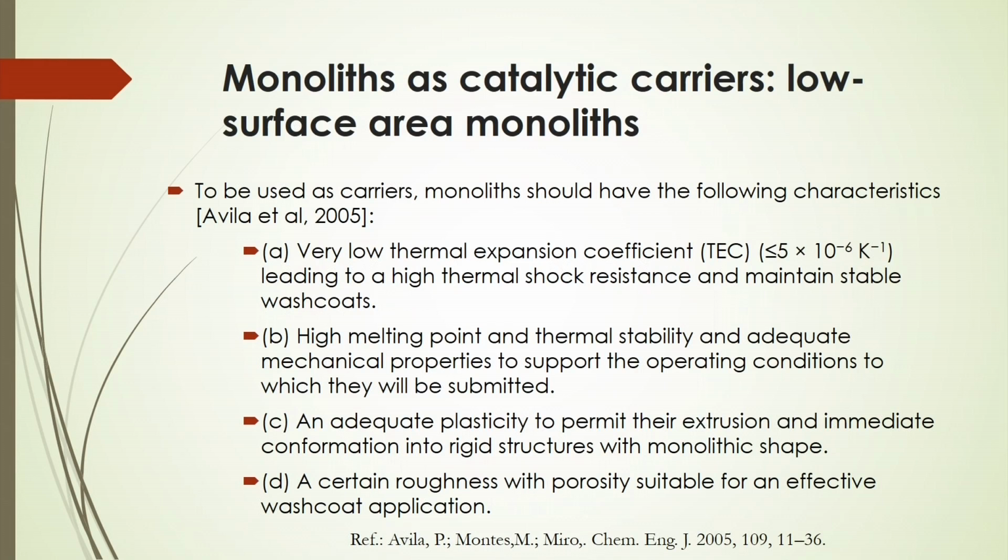High melting point and thermal stability, and adequate mechanical properties to support the operating conditions to which they will be submitted, and also adequate plasticity to permit their extrusion and immediate conformation into a rigid structure with monolithic shape. A certain roughness of the porosity should also be suitable for effective wash coat application. So, these are the different characteristics of monoliths which can be used as carriers.